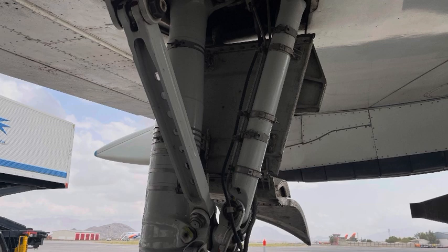The side strut prevents the landing gear from moving to the side, mainly in the main landing gear, and then the drag strut prevents the landing gear from being moved backwards and prevents the landing gear from collapse, in fact after landing and mostly during the takeoff and landing roll.